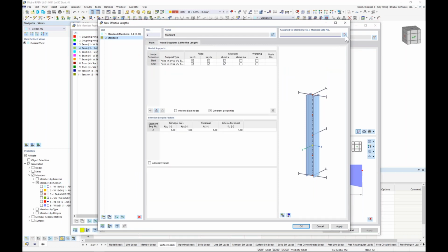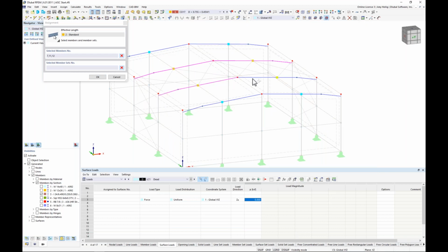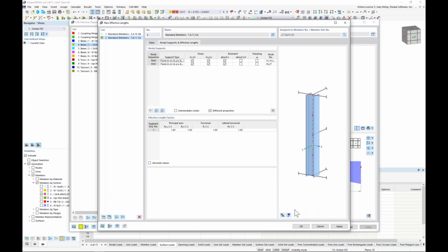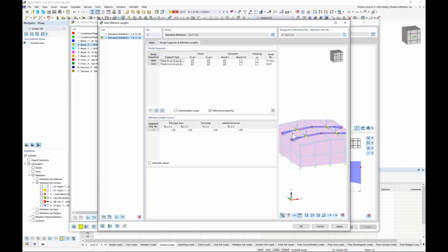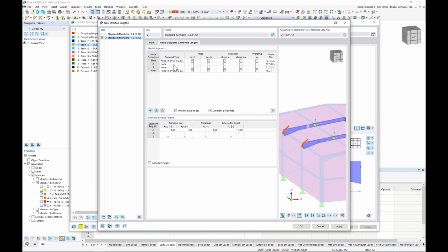And under the second tab, remember, again, I like to graphically select these. Not necessary, but I think it's helpful in determining where you're at along the length of the member. So we're going to have the program automatically detect the intermediate nodes. Two additional rows are given to us here. Now this is slightly different. The first node, we can leave as default.